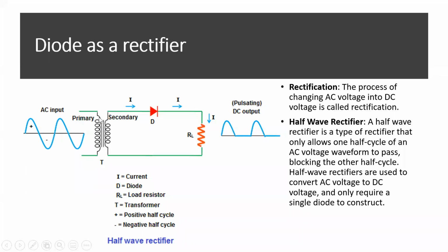Yeah, during the negative half cycle, the direction of current changes. So up you have negative and down you have positive. So the current is going from positive to negative. It is flowing from here to here, and it's coming here. Can the current pass through the diode? It's coming like this. Current is not flowing now along the blue arrow mark. It is coming in the opposite direction. Can it flow? No, because it is reverse bias, right?